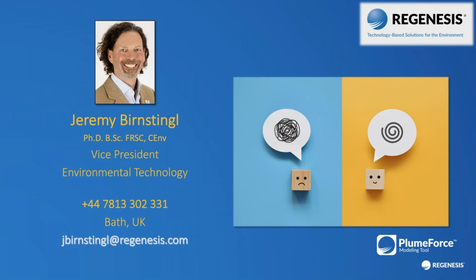PlumeForce at the present time allows up to 22 named species to be modeled in parallel. And in addition to this, there's an allowance for competing organic matter to be put in there. On top of this, it's possible to enter a full spectrum of sculpted competition to account for best estimates of unknowns. I mean, that's almost a webinar in itself. How we make these estimates of what else is there is another story. But the software has the knobs and dials that enable us to account for a smaller or much greater body of other PFAS species of a range of different competing sorptivities and other unknowns.